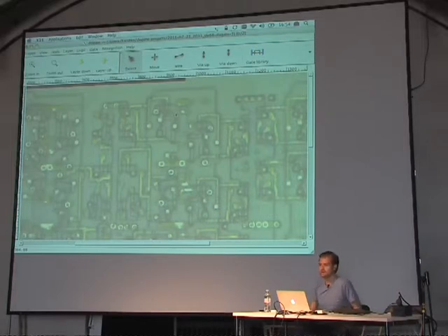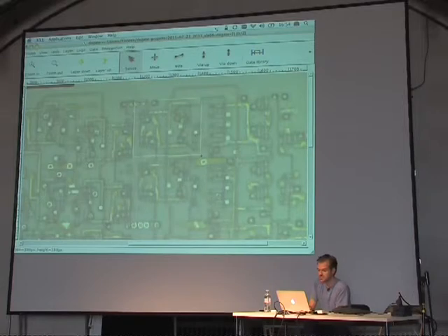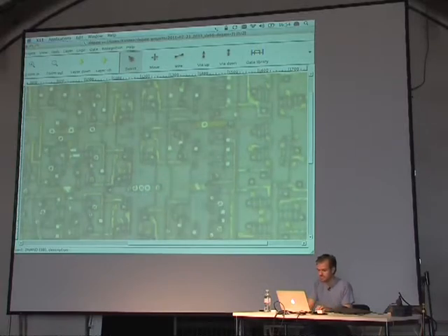With almost all, especially more modern chips, the gates are neatly separated in rows, and it's very clear where every gate starts and ends. So you would start by marking one of these gates, and tell the tool, okay, I think this is a gate. Try to find other instances of the same gate, and it will do pattern matching and say, boom, here's one, there's one, there's one. And so you get some coverage, and then you start searching for the next one. You again let it search, and not much later, you have full coverage of your chip.